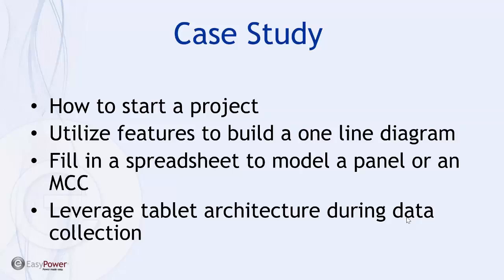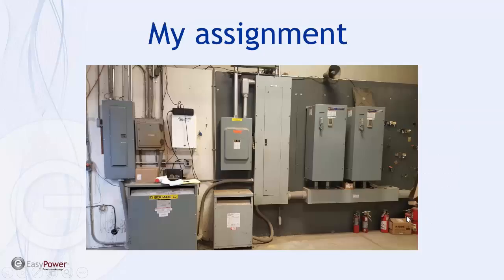So primarily I'm going to work with the basic templates in OnSite, and I will focus primarily on data collection for arc flash. But as we go through this, please consider the alternatives if the collection process is constrained by plant shutdowns. It might be wise to collect data at some other time or in different parts of the plant until you have access to energized equipment that may not normally be accessible.